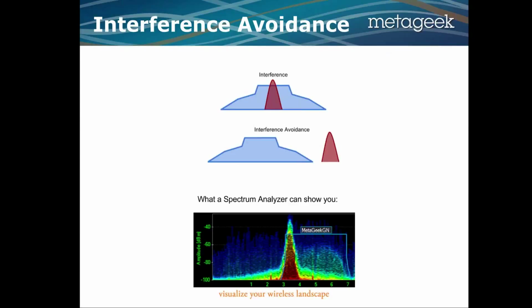And we take that and we say, okay, you have a Wi-Fi network here and it's on channel 5. That's not a standard channel, and this is going against my rules, but I just needed to create this visual image so you can understand what I'm saying. So we have a Wi-Fi network on channel 5, and then we have a non-Wi-Fi transmitter that is taller, that means it's louder, and then the color represents how constant the noise is. Now red represents constant noise, so when you see red, that means stop. This is bad. This is something that is loud and constant like an air horn.